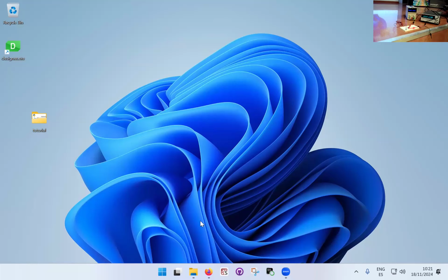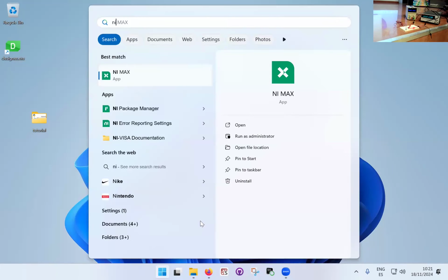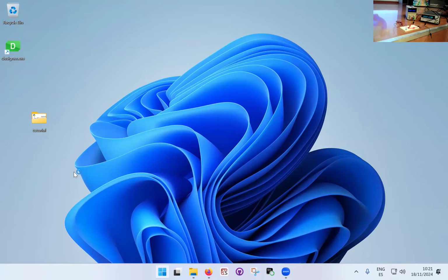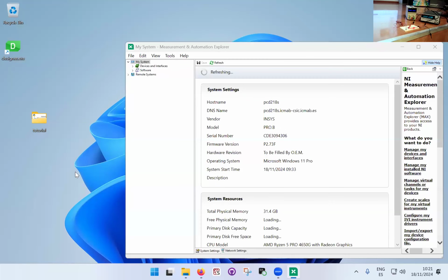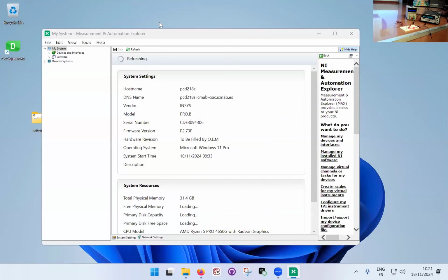Because we installed this National Instruments VISA protocol, this NI VISA actually comes with a utility called NI MAX, which, since it's already installed, you might as well use. So when you click the NI MAX software, it will come up with this little window, and this window will list all the equipment that is connected and available for Windows to talk to.